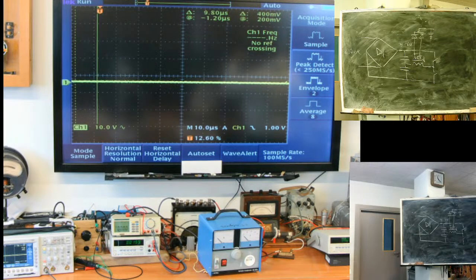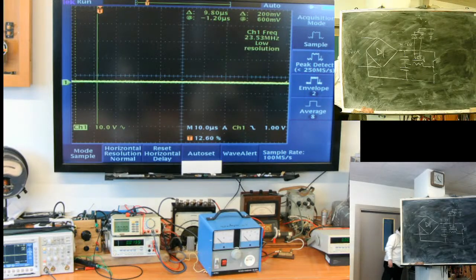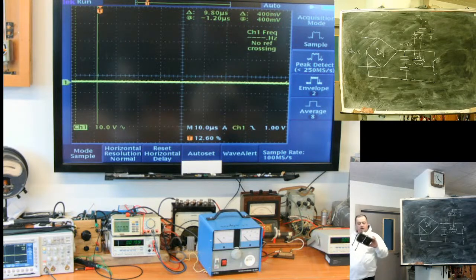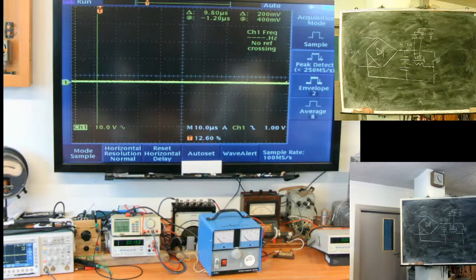For a PWM driven power supply, and this one will be for an ordinary one. We will also have 1984, 5 volts, 18 amps supply, only rectifier, and this one is stabilized. You see the power losses. You see the cooling surface. Such a transformer will require such a heater just to dissipate power losses. It's a difference.